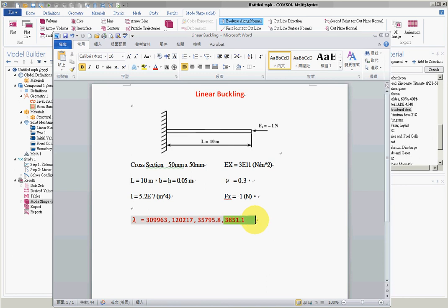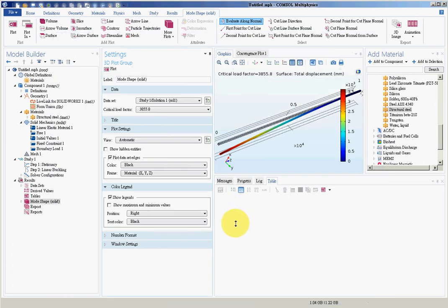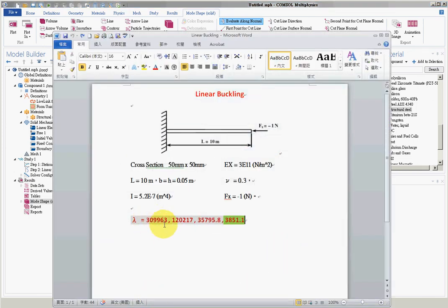So if you are comparing theoretical value in linear buckling with the CAE value, make sure that you compare the lowest mode. In higher modes, you should trust CAE instead of theoretical value, because theoretical value will deviate from reality in higher modes, since the beam is simplified into a line.